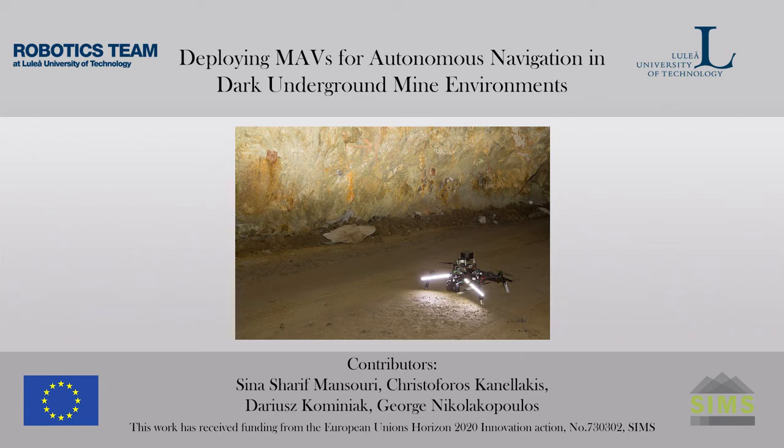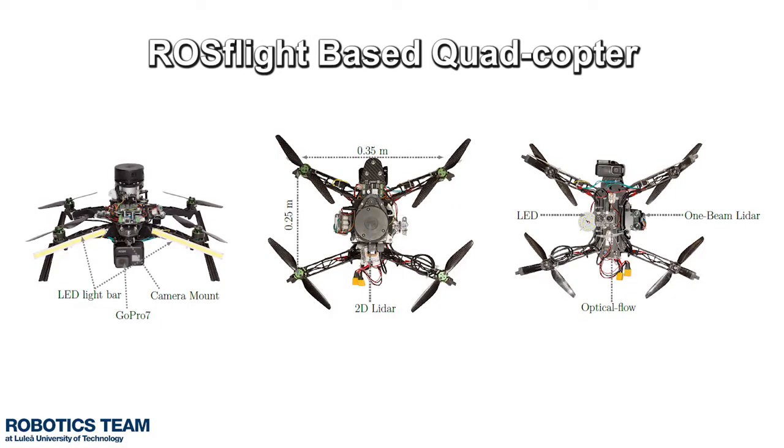This work approaches the challenging task of autonomous navigation in unknown tunnels with low-cost and consumable aerial platforms. In this work, a quadcopter is used to evaluate the proposed methods. The flight controller is ROS-Flight, and the Aeon upboard is the main processing unit. The operating system running on the board is Ubuntu Desktop 16.04, with ROS Kinetic also included.